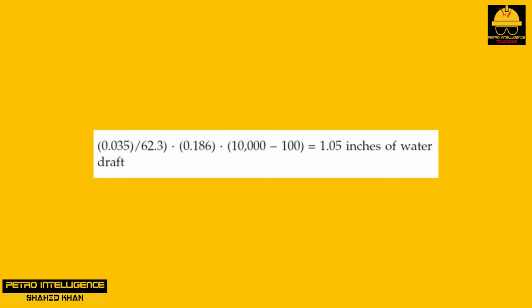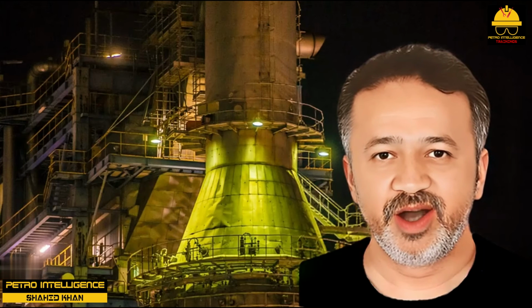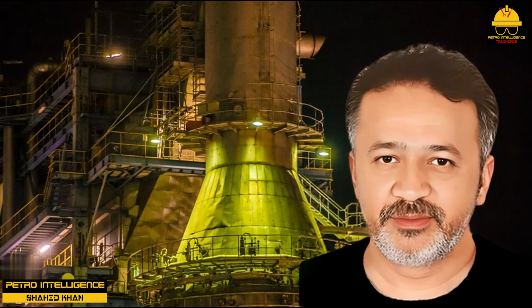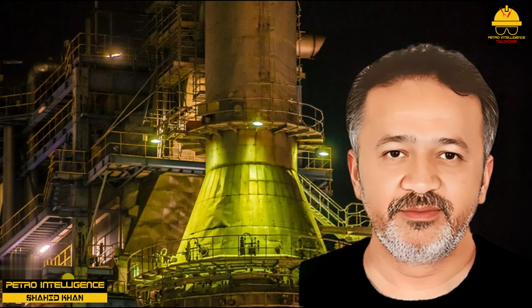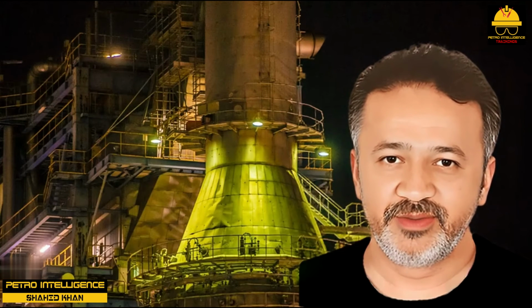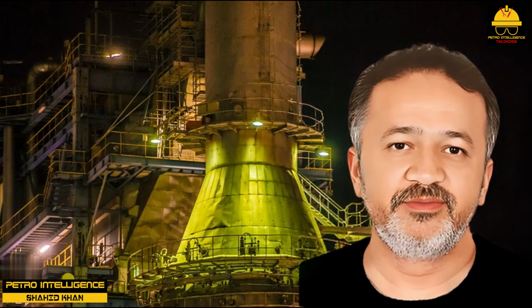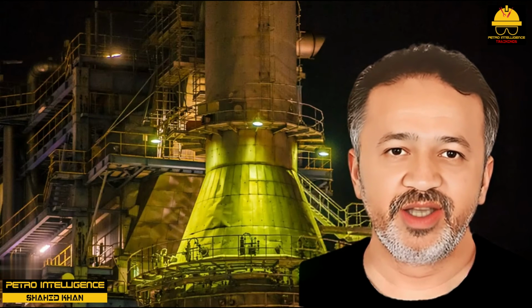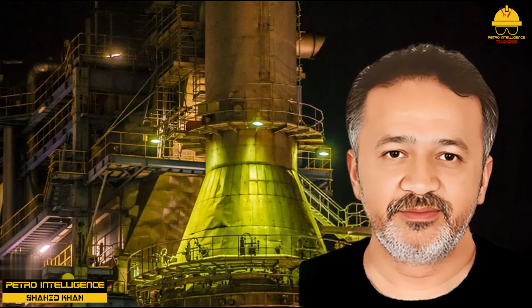The 0.035 is the density of the flue gas at 600 degrees Fahrenheit, assuming its molecular weight is the same as air. Caution: based on the roughness inside the stack, some or all of this draft may be lost due to friction. We asked the local guys running the boiler why they thought the top portion of their stack was so narrow. They simply answered, "This is the way it's always done. It is our tradition handed down for generations."